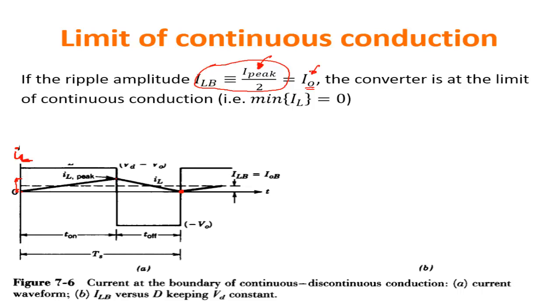This is very important in practice, because in modern electronic systems, you have strong variations of the power absorption. For example, you have a device which goes in standby mode, and then it strongly reduces power consumption, so that you can easily go from continuous conduction to a state of discontinuous conduction. Okay, let us look into the detail.